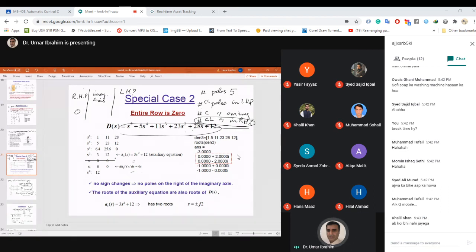Now there are 5 total poles. Do we know that all the 5 poles are in the left hand plane? No, sir, we don't know. But we do know that two of the poles are from the pure even polynomial. If two poles are from the pure even polynomial, then they have to follow the restriction that both poles must have their mirror image across the origin.